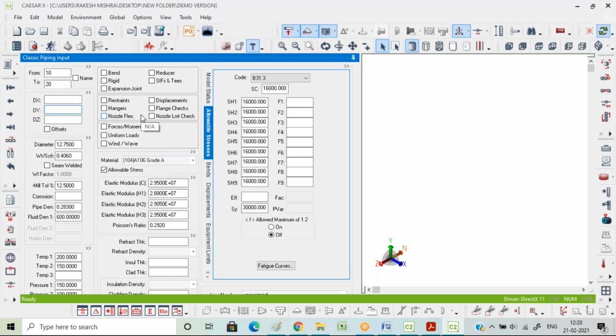You have to fix everything. What is the unit? Whether your Z is vertical or your Y is vertical, what your restraint loads are, what your stiffness loads are, the stiffness for the supports. You have to fix all of those. What is the default friction coefficient? You also have to fix this value. Everything has to be fixed in the configuration file itself, and then you come to this file. But we are skipping that step right now.